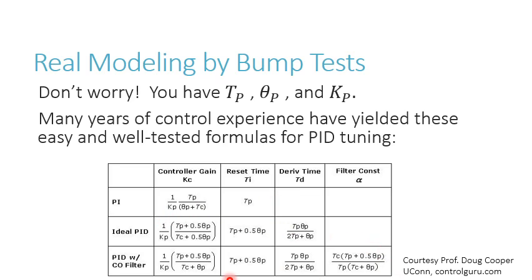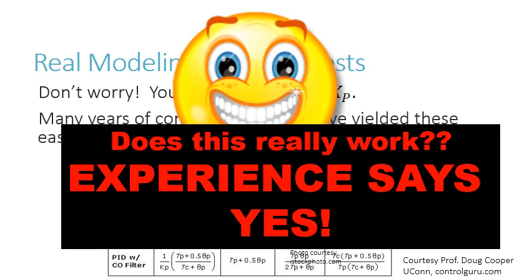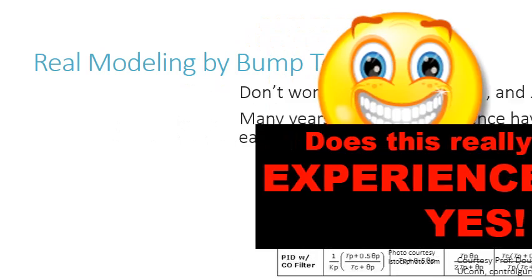Now you might wonder what's the theoretical basis behind these. Well, some sets of formulas are purely empirical. This was derived in the 1980s from internal model control, which is a Laplace domain method. So these do have their roots in Laplace domain analysis. But from the point of view of practitioners, you don't really need to know that. What you really want to know is how to tune your PID controller, and it's pretty easy to do, as you can see. And the question you might ask is, does it really work? Well, yes, it has been in major industry for a long time. Yes, it does work as long as your process really comes close to a first order plus time delay model.